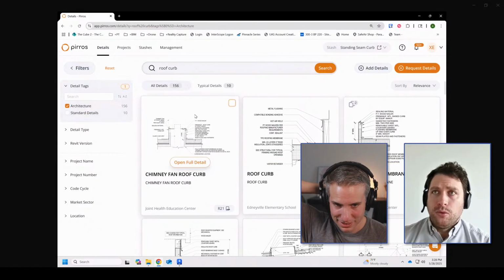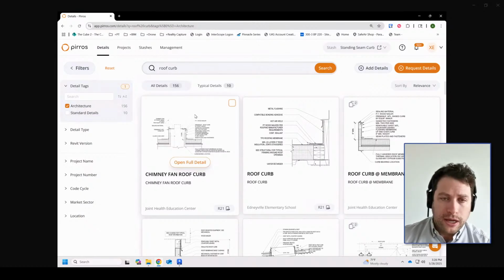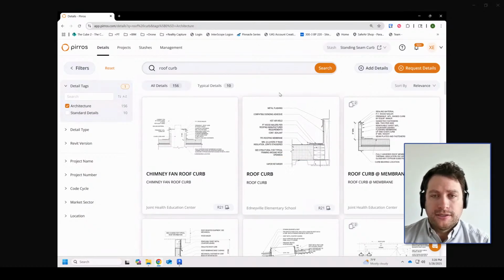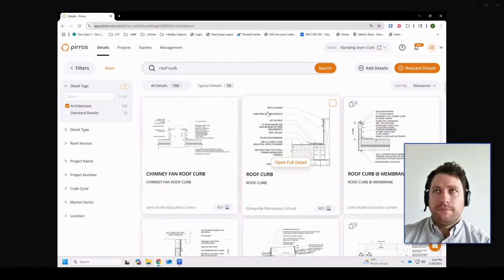Yeah, and what Talar, our account manager, has taught us is that what it's showing right here is it's actually created a PDF of that view that's on the sheet. So you're seeing what was actually issued, which is great. It doesn't necessarily mean that's what you're going to import into Revit. If it's a drafting view, you'll get all of that stuff. You only get to bring the 2D stuff into Revit. So if you have a 3D element that's being shown in a detail here, you'll see it in this thumbnail, but it won't actually be imported into Revit, which is understandable, and that's fine.